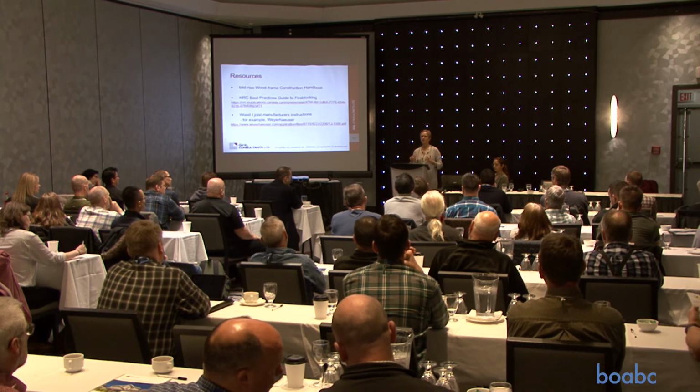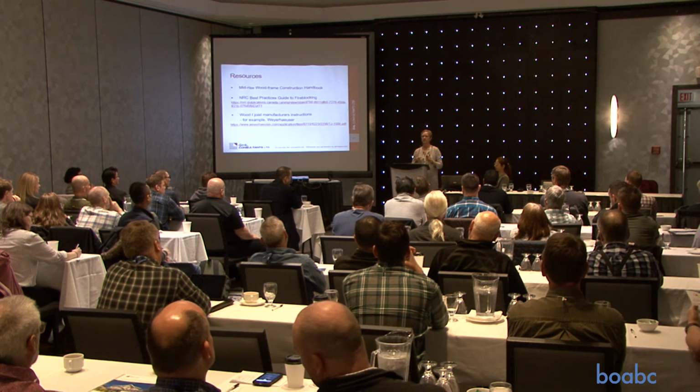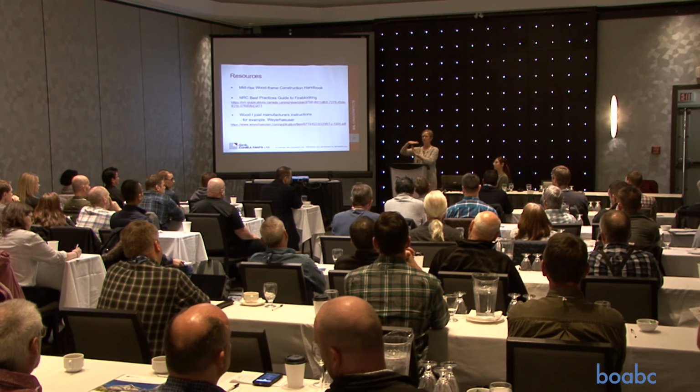So he said, the building code says, and we always have, that the joint we're talking about is the ceiling gypsum board to the wall gypsum board, and the new building code coming out says you don't have to fire stop that joint if it's backed by solid lumber.